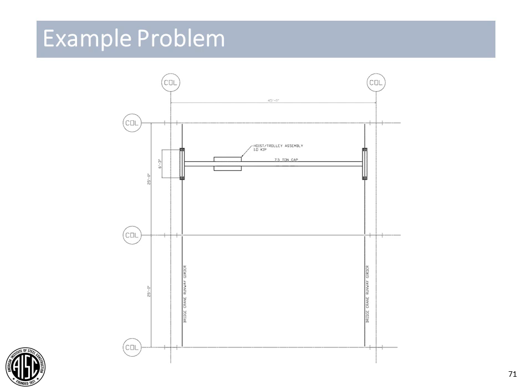So this is just a plan view of our design. We have a superstructure that has bays at 25 foot on center. We have a 7.5 ton underhung bridge crane system. We've got our 2 end trucks that have wheel spacing at 6'3". And then this is our hoist and trolley assembly, which has a 1 kip dead load.